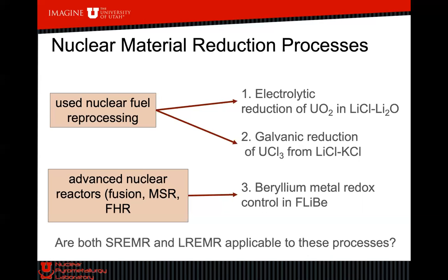And then finally, I'm going to look at the coolant application. This is like advanced nuclear reactors. I'm not going to necessarily look at the MSR so much. In this particular case, I'm looking at the FHR, which is the fluoride salt high temperature reactor. It's the salt cooled reactor. This is when we've got pebble fuel, which is going to flow this salt through it as the coolant. And interestingly, that also applies to fusion. There's a concept for a fusion blanket that involves this salt.